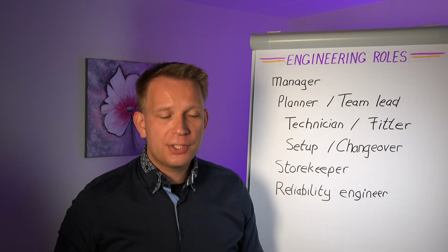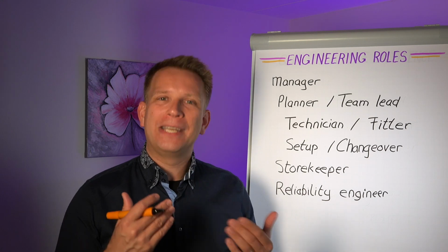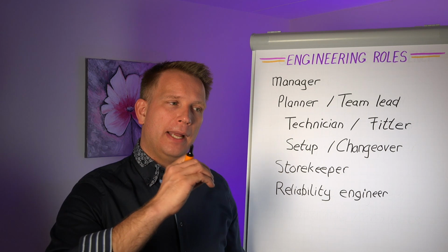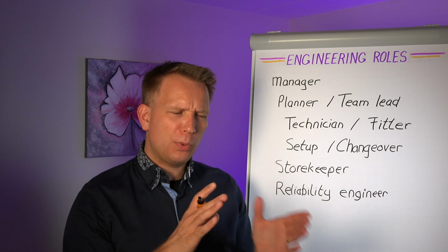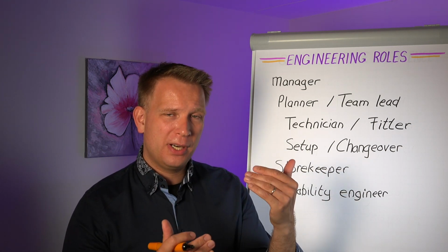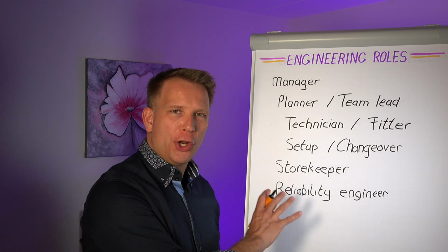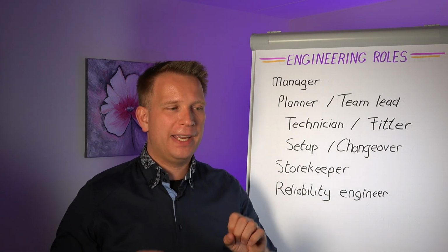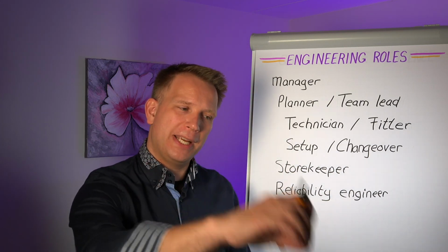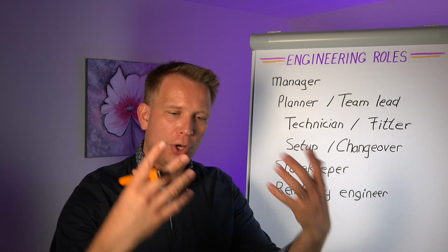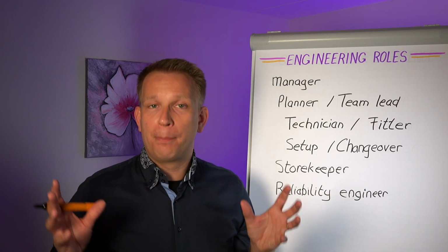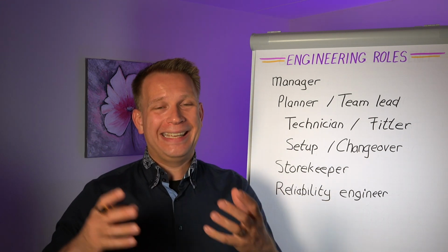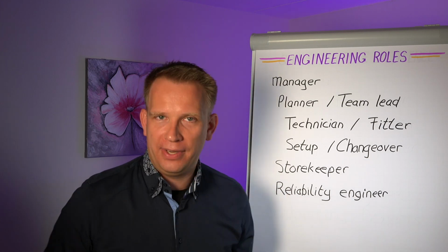These reliability engineers will also quite often have some interaction with process engineers to find the better settings. Where a product or a process engineer will find a setting like which pressure, which temperature, it's already with a lot of link to a reliability engineer to say, okay, how many products could this machine do? What's the speed of this conveyor? How much pressure can we put, not per se on the product part, but on conveyors, on setters, on all kinds of parts of the machine to make sure that they work in sync, that they don't get overburdened, that you don't get any excess wear and tear.